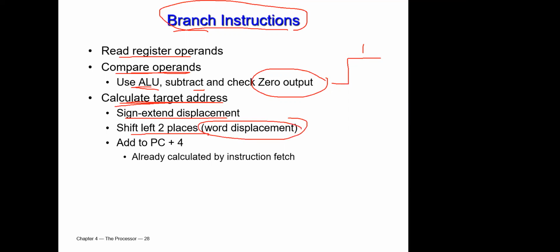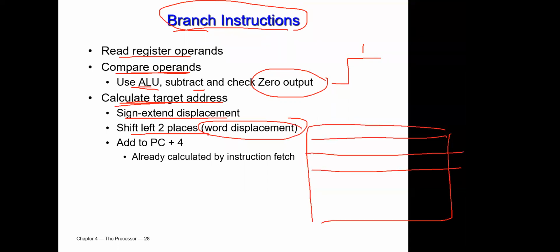If you remember from one of the lecture slides, with the branch instruction, when I write 2, we mentioned that it should be 2 multiplied by 4, and then I need to do the sign extension, correct?